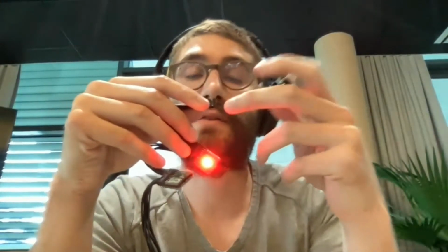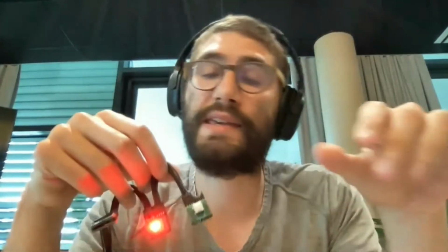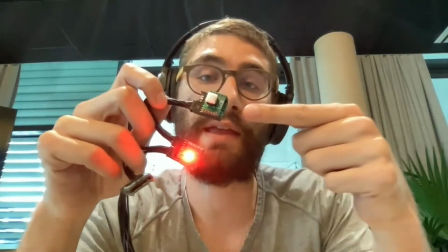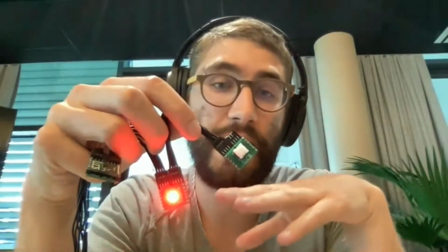In this specific case, we can deal with hot plug. Luos never makes dynamic detection by itself. So it is your work as a developer to choose when Luos runs a detection. In this specific case, when I add this board here, if after something like 30 milliseconds no one detects this board, it will make its own detection. After this new detection, all the boards on the system know that there is a new board with this service on it and can use it.